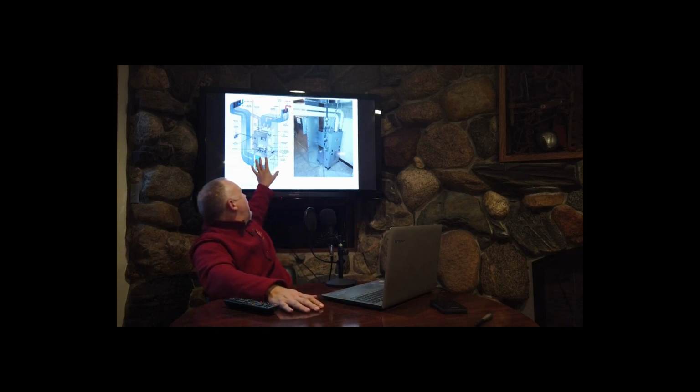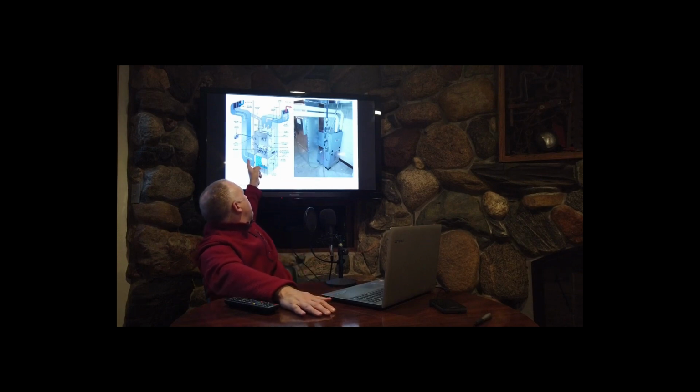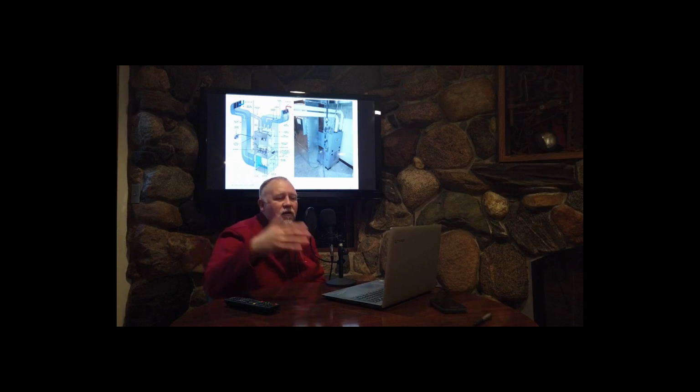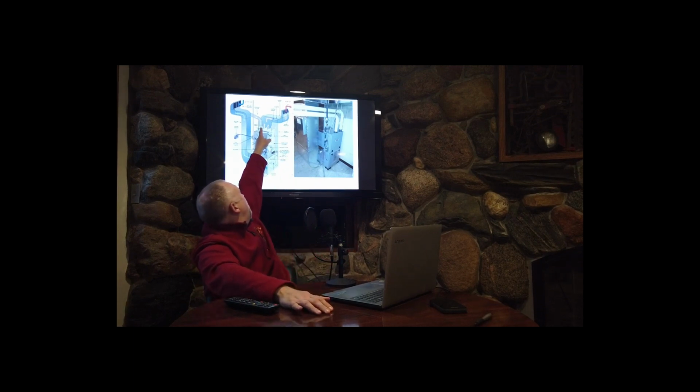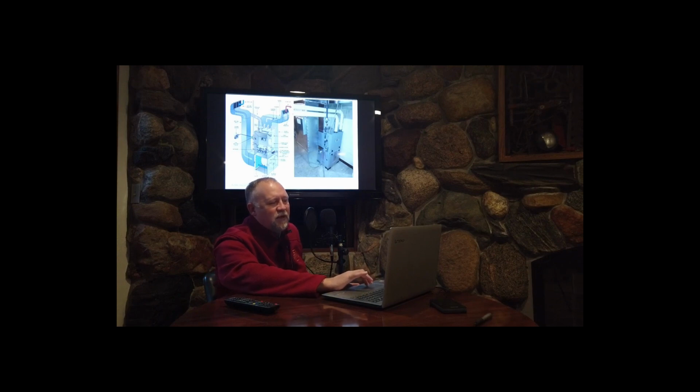All right, so let's look at this cutaway. This illustration shows all those different parts. Here's the return air. Here's the fan on the bottom. It blows air through the heat exchanger. The space air goes on one side of the heat exchanger and back to the room. The combustion air goes on the other side, and then the junk, see where it says draft hood and exhaust stack, that goes outside. This one is drawn with a metal piece, though. That's the only difference between these two pictures. And if it's metal, that means it is a lower efficiency furnace. It's less than 88% efficient.